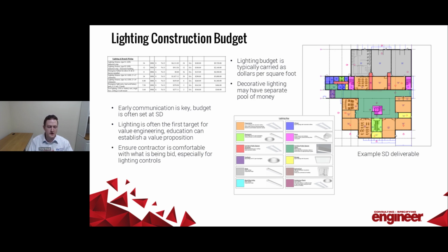So I'm going to be looking for maybe more flat panels. Instead of high quality downlights, maybe I'm doing more of a surface mounted edgelit sort of situation with downlights, but always looking for ways, especially in those fixtures where you're using the hundreds of fixtures, your type A's, that you're conscious of the budget so that you're not specifying a high-end product when the budget is not there.